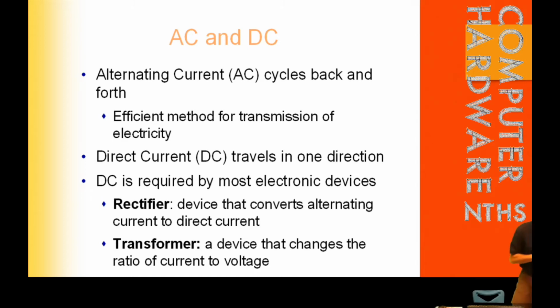Every single time you plug in a laptop power supply, you're plugging the AC plug into the wall. This power supply is acting as a transformer to change the voltage from 110 to the output voltage of this device, and it rectifies it from AC to DC. So in the end, what you have here is a DC plug that has a very specific voltage on it. If I could read, it would say the output voltage on here is 19 volts. So it goes from 110 to 19, and it changes it from AC to DC. And that same thing happens in every one of your iPhone or Android chargers. Any place you put a power brick in your house, it's changing it from AC to DC.